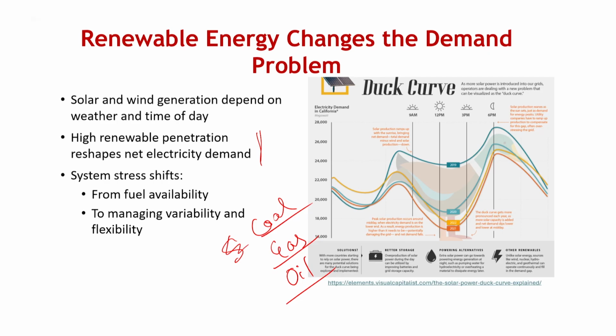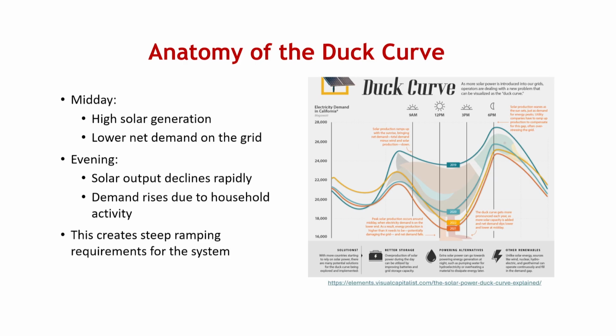So there is a classical curve around this for solar, which was first developed in California. It is called the duck curve. Let me come to you here. You have your energy requirement. Suppose the energy requirement is this, let's assume it is flat. But your solar generation is happening more during this period only. Since solar generation happens only during a specific period, there is effectively no solar generation before 9 AM, and effectively no solar generation after 6 PM.